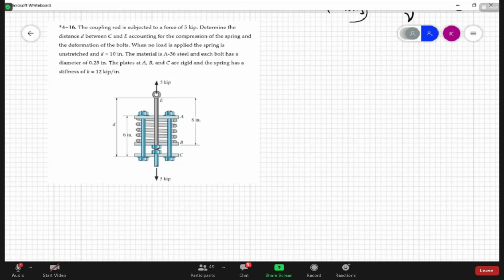So when you see this, whether it's something geometrically confusing like this because it has the springs, or maybe it's one of those problems where you have a gap, what you really want to do is think very carefully about what's going on kinematically or geometrically. And also draw more free body diagrams, because that's the key that unlocks the door to a lot of these problems. Sometimes you have to do more than one, or even more than two free body diagrams.